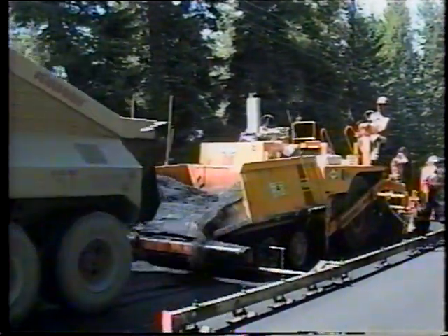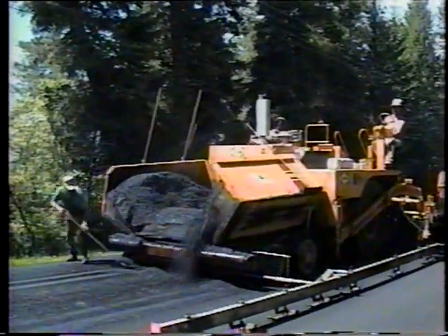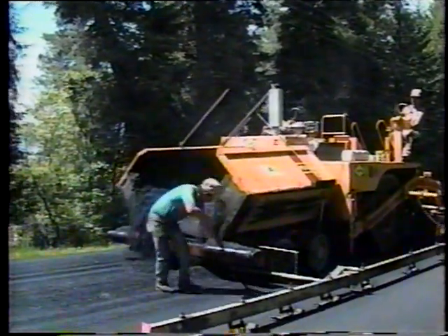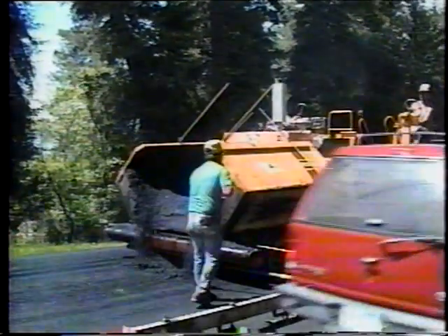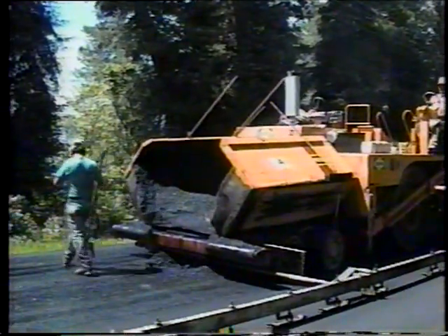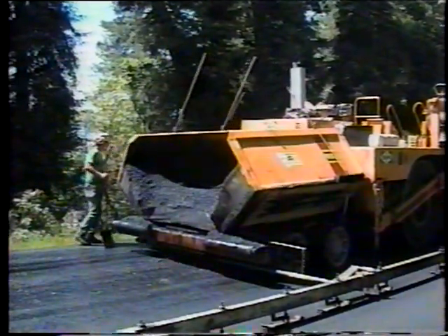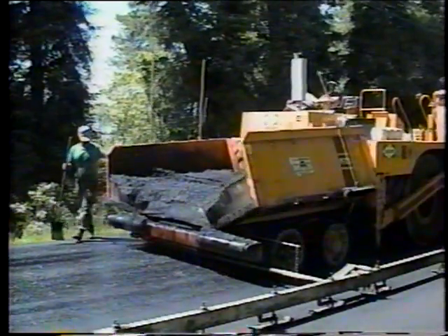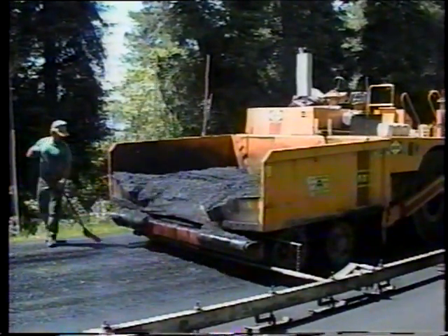Another concern during placement is mix sticking to the sides of the hopper. What we want to avoid is cold, hardened mix mingling with good mix. Some people insist that the wing should be raised and lowered after every truckload. Others maintain that the wing should never be moved. Both arguments are valid, and either practice should be allowed, provided that only hot mix is used in the pavement. So if the wings are raised, there must always be ample mix on the conveyors for the wing material to mix with.